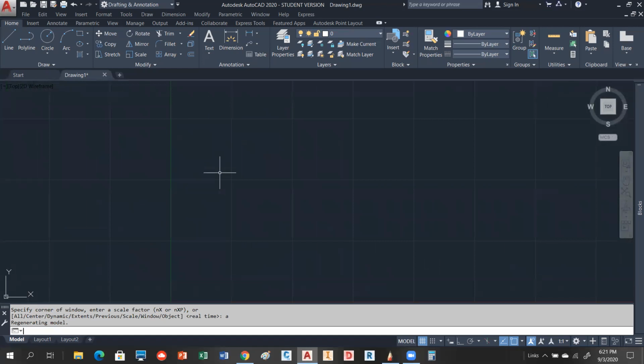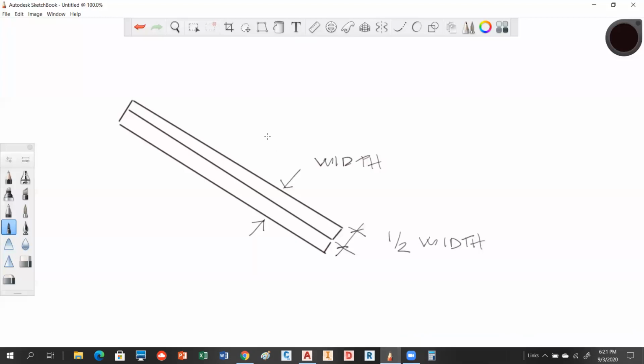So it'll zoom us out like that. So I want to now talk about the concept of an open polyline versus a closed polyline. If we think about what we mean by closed polyline, in a typical polyline, I've got a line here to here, and if I draw that back to the starting point, I would say that line is closed.